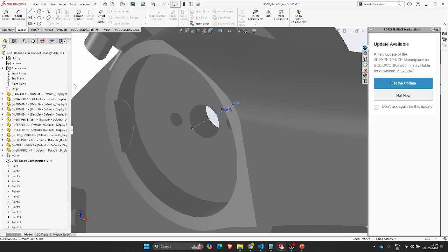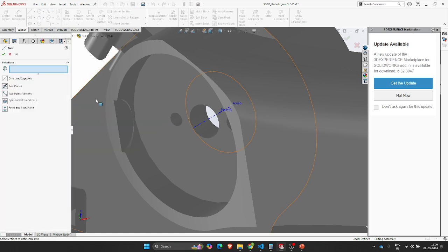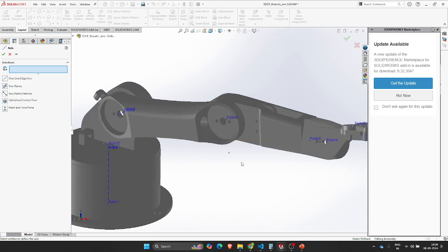Click on yes, this is where the axis of rotation would be coming there, and press escape, then go to insert once again, axis. To make it not so confusing, I could always copy the previous axis, paste it there, and rename it. That is up to you, how you want to minimize the time, as in how you want to optimize this process.